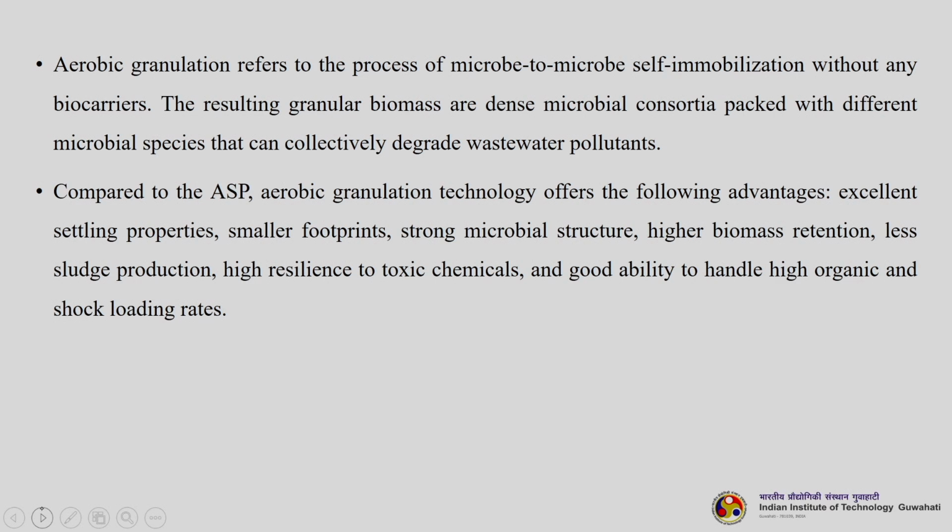It has excellent settling properties, smaller footprint, a strong microbial structure, higher biomass retention, less sludge production, high resilience to toxic chemicals and good ability to handle high organic and shock loading rates. So, this is all about how you can reduce the MBR fouling, basically fouling in the membrane bioreactors.